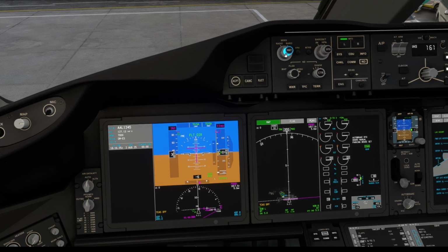So this is basically the height where, in case of an engine failure, would be the earliest point where we would accelerate and could clean up or start with our aircraft cleanup, which means putting the flaps back to up and establish a clean flaps up, no drag configuration.